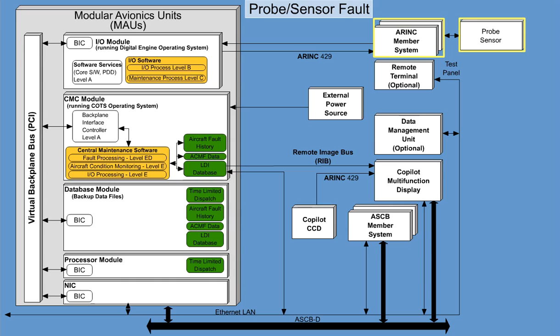A smart member system LRU reports a possibility of a non-smart LRU at fault. This situation occurs when the smart LRU is not able to determine if it is sensor number 1 or sensor number 2, or an actuator or proximity switch, for example, which has failed. All LRUs are from the same system.